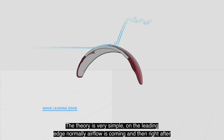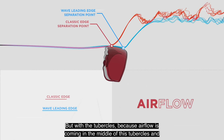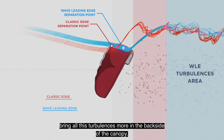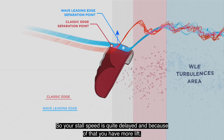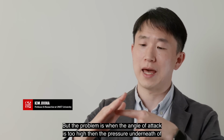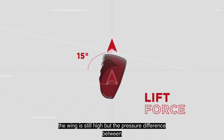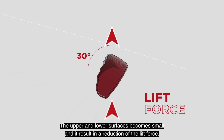At the leading edge, normally airflow is coming, and then right after you get the separation and create the turbulence. But with the tubercles, because airflow is coming in the middle of these tubercles and brings all this turbulence more to the backside of the canopy, your stall speed is quite delayed, and because of that you have more lift. But the problem is that when the angle of attack is too high, the pressure underneath the wing is still high, but the pressure difference between the upper and lower surfaces becomes small, which results in a reduction in the lift force.